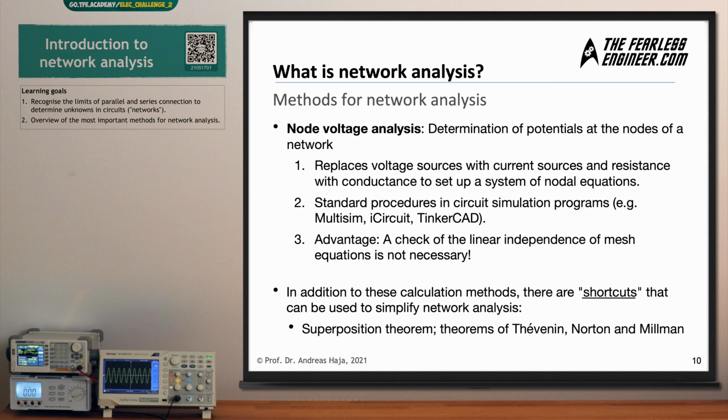If you use 2 equations which enter the same information into the network, this will result in an unsolvable network. And this check for linear dependency has to be performed manually by you if you select equations, but a computer is hard pressed to do the same. It can be done, but it's time consuming, and this node voltage analysis circumvents this check for linear dependence.